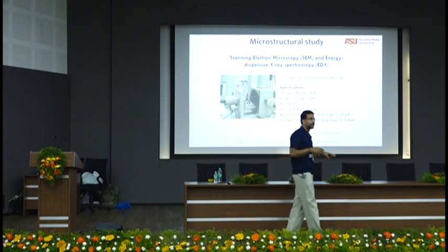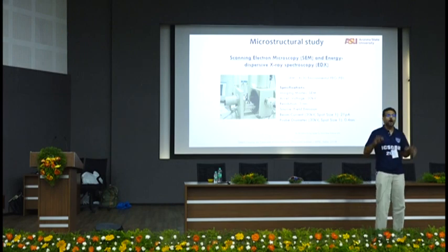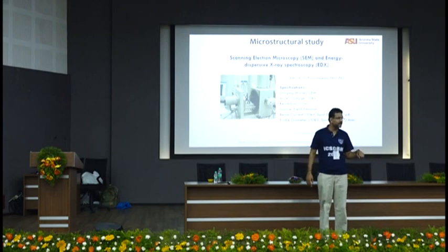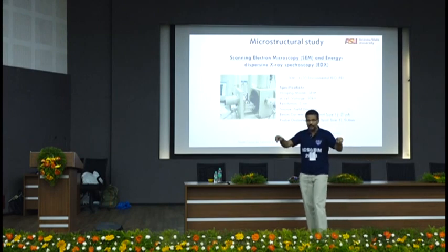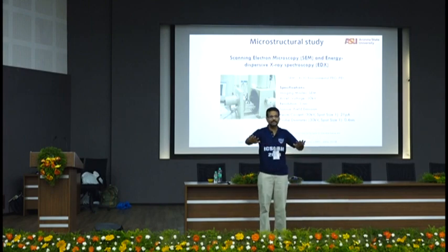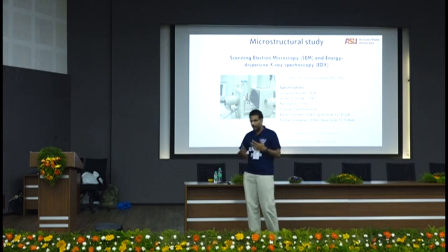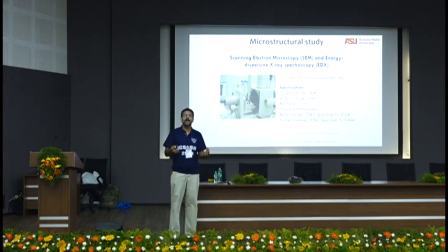So for anybody who is doing geopolymers, anybody who is doing fly ash geopolymer, all you get is Q4 silica. Why? Because the silica in the fly ash does not change its state. All it's doing is replacing some silica with alumina and some sodium, right? So it'll all be Q4, the natural state of silica will be there. If you're doing normal CSH, you will have a lot of Q2 and Q3 silica, very little Q4 silica, because your actual silica structure will be completely decimated. And that's why from 3D you're going to 2D. Your actual silica structure will be completely broken down because of the abundance of calcium ions. Okay? So you can know from that what is the actual structure at an atomic level.